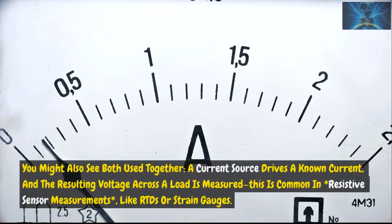You might also see both used together. A current source drives a known current, and the resulting voltage across a load is measured. This is common in resistive sensor measurements, like RTDs or strain gauges.